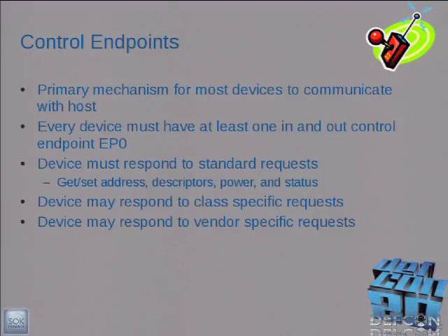So the devices can also respond to specific class requests for the class of device and optionally vendor requests. So you could, in theory, have a very special driver for your kind of mass storage device. In practicality, nobody does that because nobody wants to rewrite the drivers.